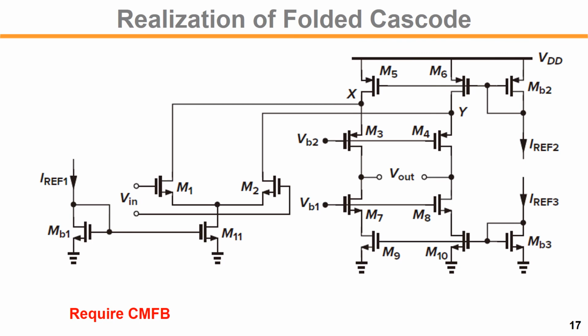this is more detailed realization. So for the current source we had is M1, and then the input side tail current source, and then we also have a cascode side, we have a bottom current source and top current source. So when you look at the circuit, you have to identify what is the current source at first. So if you have a current source at the top and bottom at the same time, this requires always the common mode feedback, because the current source impedance is so high, and so we would have a large output impedance,